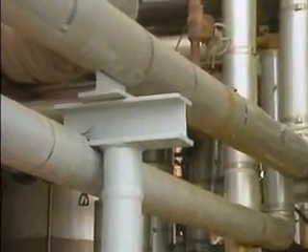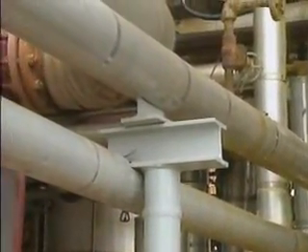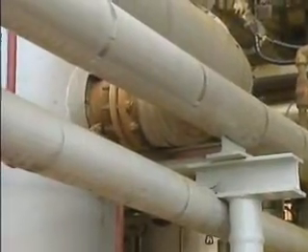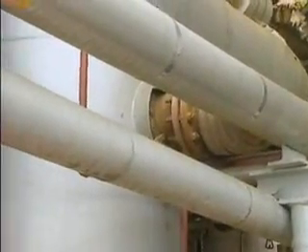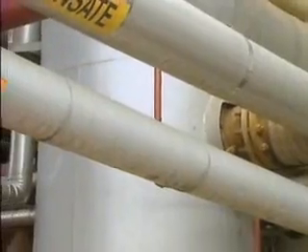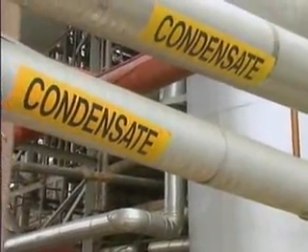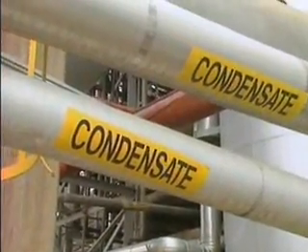On the other hand, in piping systems that have sufficiently large return piping, a failed trap may cause no rise in back pressure, and the temperature differential would remain unchanged. So this is another situation in which measuring the temperature differential across the trap won't detect the trap failure.